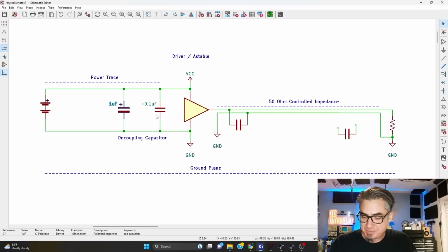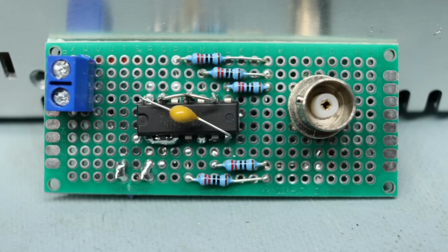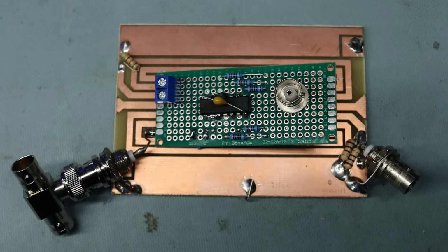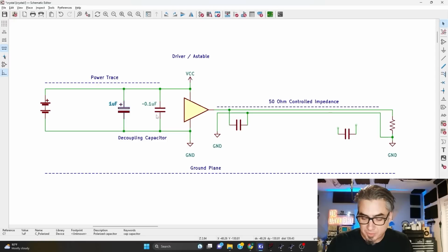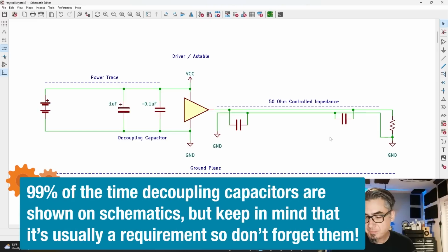I had an idea how to demonstrate this, and there are a couple of really good examples online that are parallel to what I was trying to do here. So I actually made 2 of these boards. This is an astable oscillator made from 7400 logic. And this is the second board that I made, and I destroyed it. I guess I shorted something out while I was probing around. So unfortunately, I can't demonstrate that. It's a good thing to keep in your bag of tricks. Sometimes schematics don't show the bypass capacitor, but it's an important part of any digital circuit or even analog stuff.